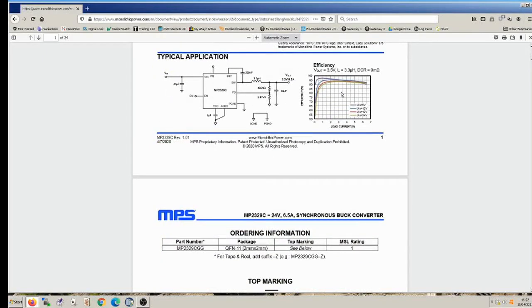That's the device. And if you see one of these, anything like that again, just search for MPS and then the first 2 letters. Hopefully, if you know what it is, like a buck regulator, that'll help. And that's how you'll find these things. If not, you have to do like I've done before: go and ask on the internet. Bad Caps Forum, and I'll show you that website. That's my favourite. And there's 1 or 2 others, and people know this stuff.